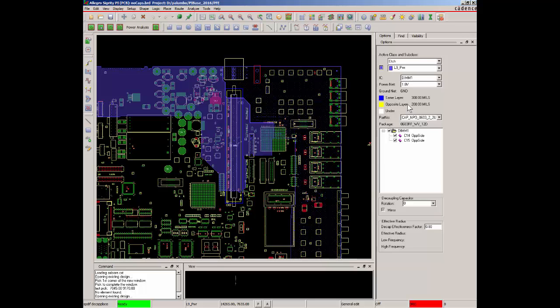In summary, we created power integrity constraint sets using the Power Feasibility Editor in one design, exported them into a technology file, and made them reusable across other designs with a similar memory controller and memory DIMM by importing our power integrity constraint sets.